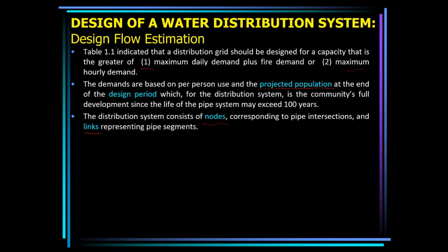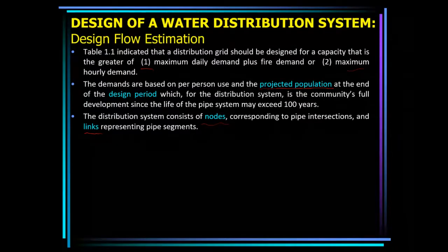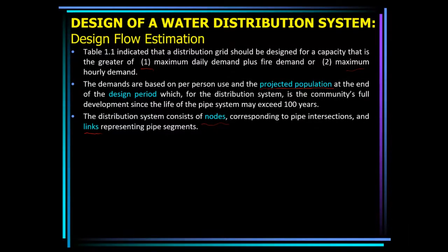That is why in the example in the pipe network analysis, you have seen the nodal demands at each node. Whenever you have more than one pipe meeting at a point, then you have a nodal demand. That is where we assume that the outflows occur. Of course, practically outflows can even occur along the pipe, but more often than not, for analysis purposes and most practical considerations, outflows occur at the nodes.